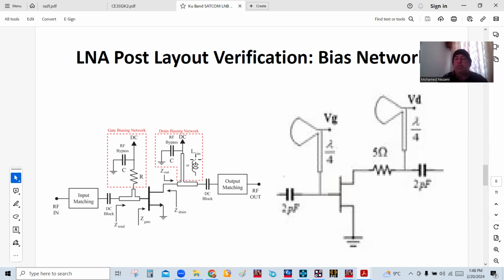And the way to do this is, of course, if it's moderate frequencies, we can use inductors, like Coilcraft inductors, some of the air-wound inductors. We pick an inductor like it's drawn in here so that the self-resonance frequency of that inductor is right at the operating frequency, so that the impedance presented to the drain is highest, while DC-wise it's 0 ohm, okay? And of course, in the higher frequencies, we really can't do that.